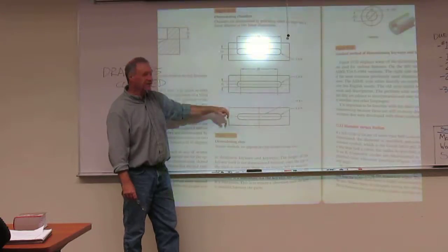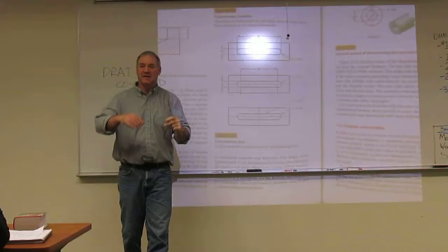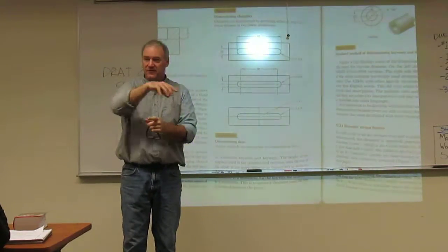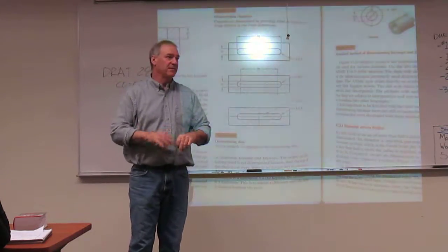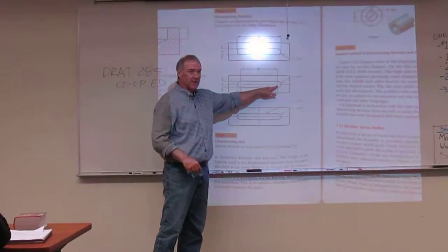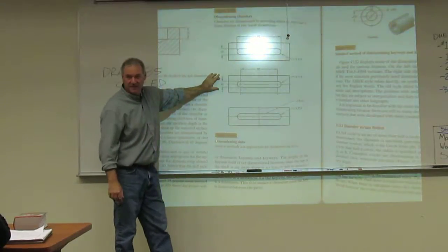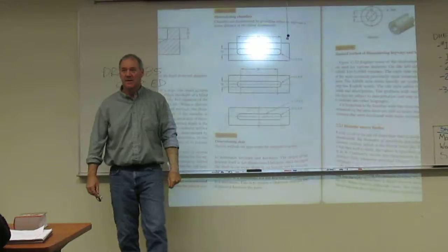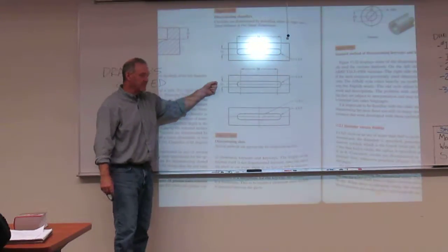And this is built on a slot being done with a router. If you don't know what a router is, it's a device that's got a drill or a cutting edge that you drop down in, and then it can cut linearly too. It's a lot like how a CNC mill works, except you're running it by hand. So here we need center to center to drop our bit in, and then we cut the trench this way. We need this size because it matches up with our bits, the special devices that do this. So this is kind of the main one most people use.